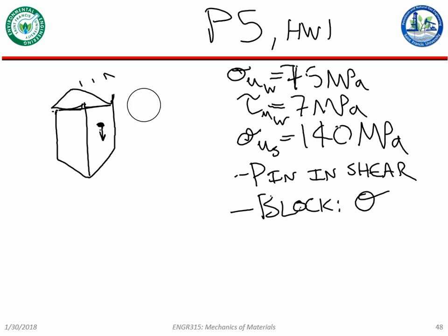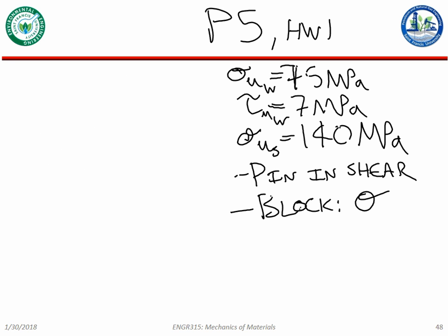Wow, my 3D is failing me. So I need to worry about, there we go. If I was to take a section of the block, I'd have to worry about your regular old-fashioned normal stress, just trying to pull the block off of the ceiling, if you will. So there's force divided by the cross-sectional area.